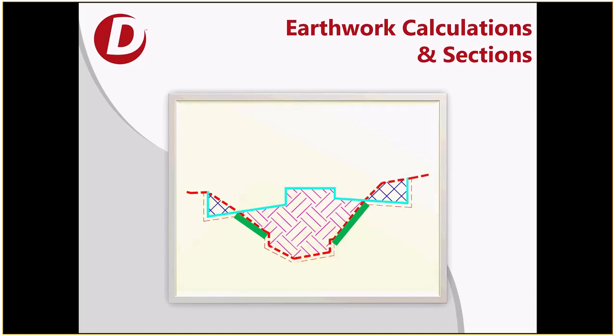So one of the things to remember about ground compaction is, if you want it to be as accurate as possible, you want to get a recommendation from your geotechnical engineer as to what that ground compaction factor could be. So you don't only have to think about this when you're setting your model up, you've got to be thinking about this way back when you're scoping the project out with the geotech to make sure that he knows that's something you're going to ask of him. And I'll tell you, they don't like to give you this because it's pretty hard to make a reasonable assumption on that, but hold their feet to the fire and make them, as the soils experts, make a recommendation on that and include that in your model.